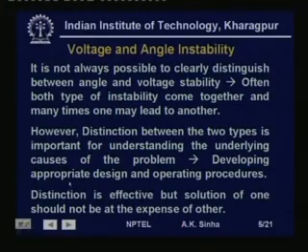Although the distinction is effective in trying to understand the causes as well as in designing the control actions for arresting instability for these two types of stability, we should not think of the problems as isolated ones, that is, voltage stability completely separate from rotor angle stability, because many times, as we have seen, one leads to the other.